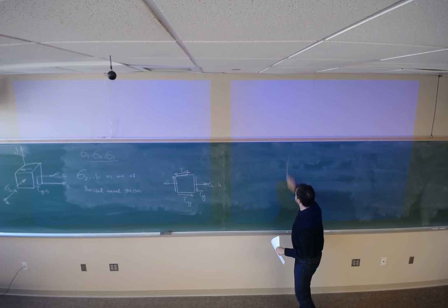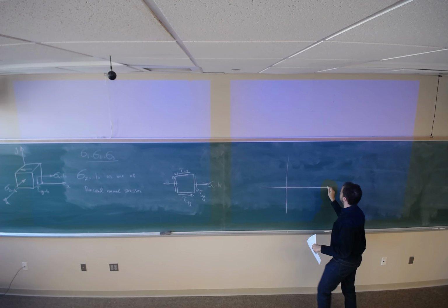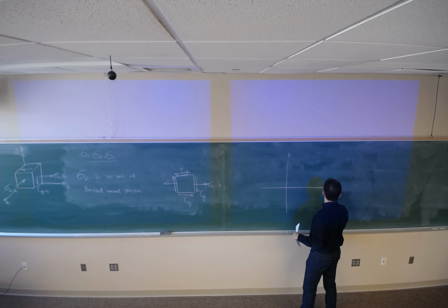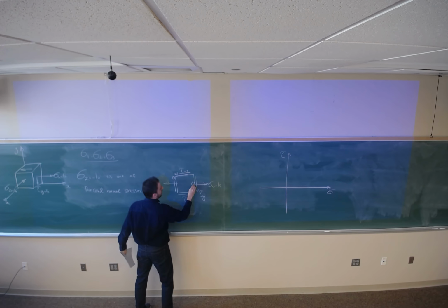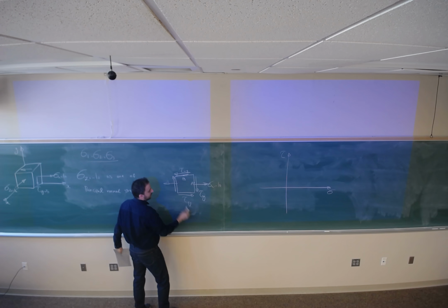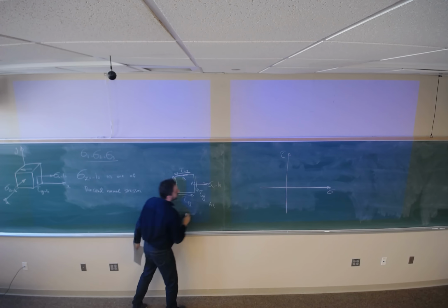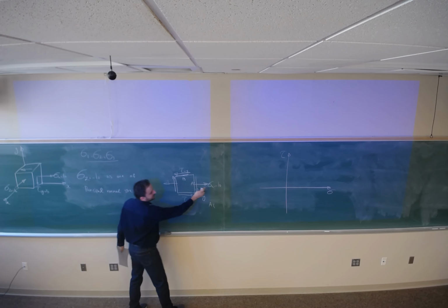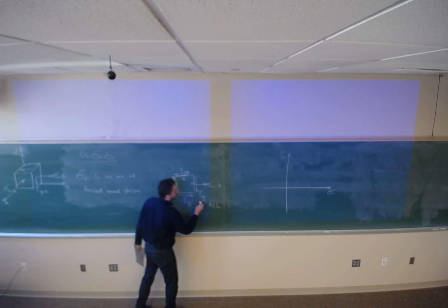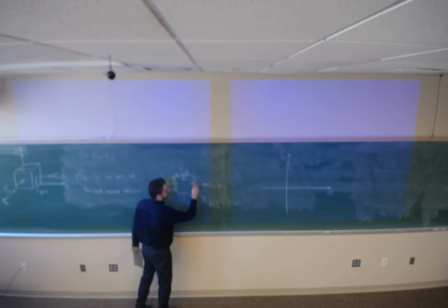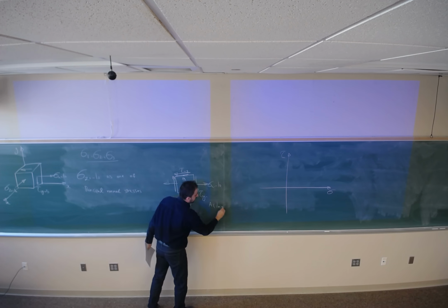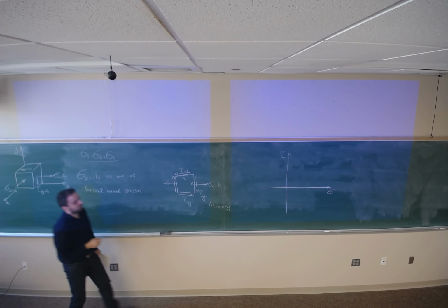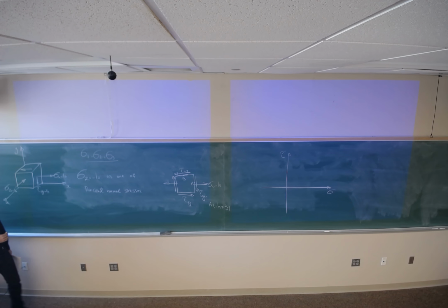If I want to draw the Mohr circle for this, I pick 2 points, point A and point B, and write the coordinates. Point A has a normal stress of 10 and 5, which is clockwise, so it should be positive on the Mohr circle.